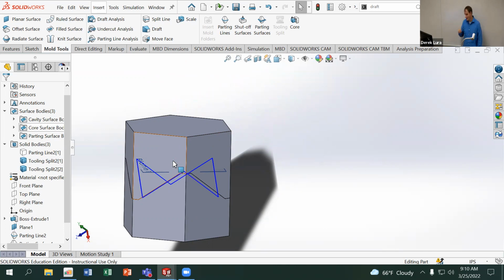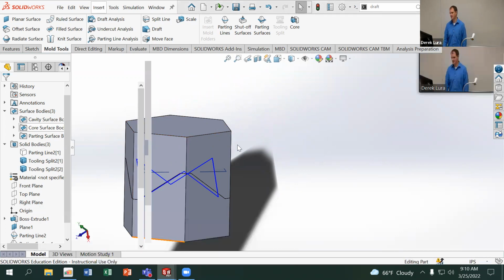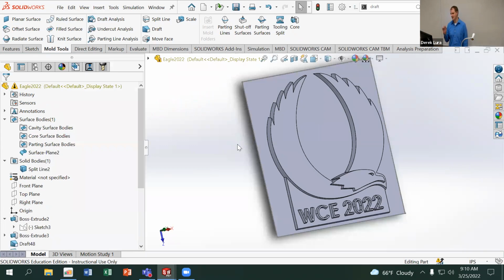All right. The other way of doing this without using the automated tools, which is where we're going to have to default to when the automated tools don't work, is you can still make the mold cavities inside SOLIDWORKS by dividing out parts. Rather than using the tool splitting tool, I'm going to make a solid body that's the size of the tool splitting cavity I used, but make it a separate body from what I have here, and then subtract those two parts to make two separate bodies, okay?